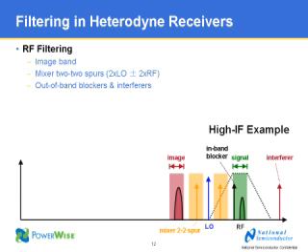Now, it goes without saying that since we're talking about a high-performance system, we're using a heterodyne architecture here, not direct conversion. As you can see on the bottom right of the slide, you have this wanted signal that's highlighted in green, and you have all the other stuff that is unwanted, including the out-of-band interferers, the image, and the mixer 2-2 spurs. Now, the goal of the front-end stage of filtering, the RF filters, is to filter the image, the 2-2 spurs, and the out-of-band blockers before they get to IF.